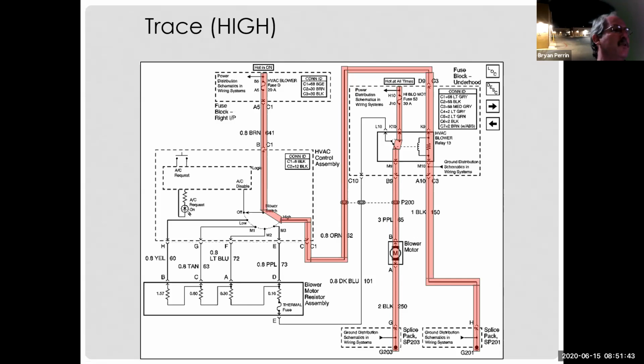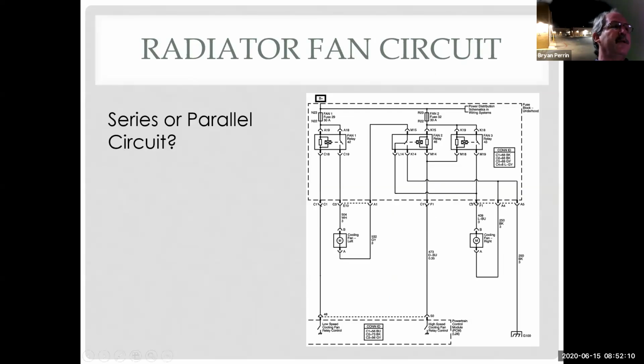And I apologize. Normally I have printouts of this and we spend a lot of time highlighting and talking about it. But again, I just want to get us thinking about, when I get a voltage reading on a meter or a scope or a power probe, is this the voltage I should have here? Don't think automatically something's wrong. I need to look at the schematic, and that's where using the highlighters is really helpful for tracing through and seeing. So let's look at another schematic here.